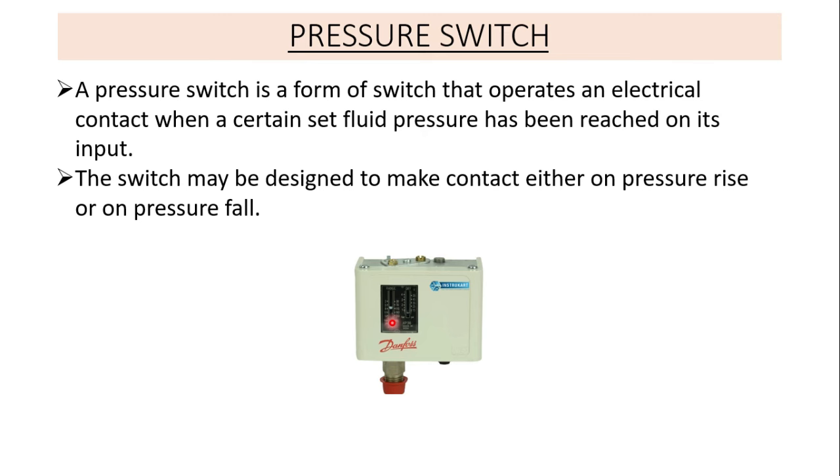What pressure you prefer to set depends on our application, like a riser in the firefighting system, a booster pump, hydropneumatic pumps, or even air compressors. According to our demands we can set it over here. Suppose we set it to 6 bar, and over here is the difference setting.